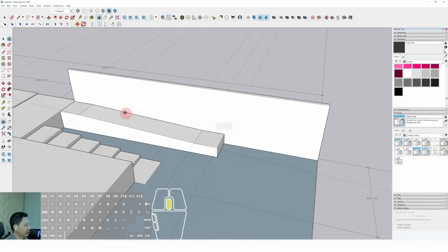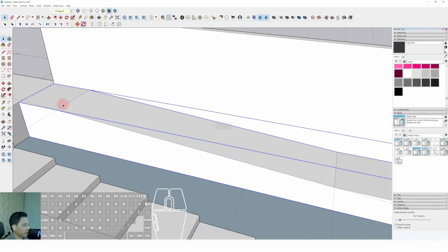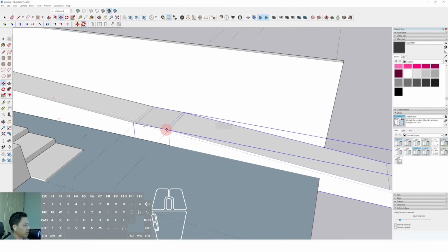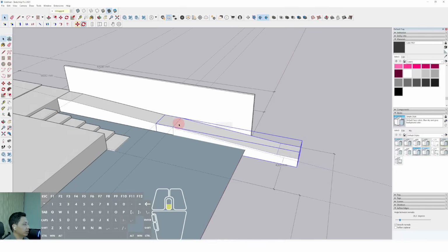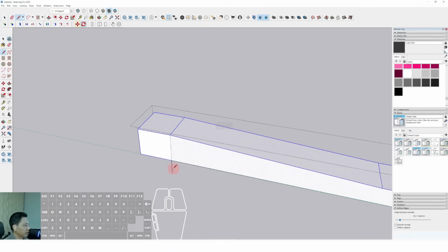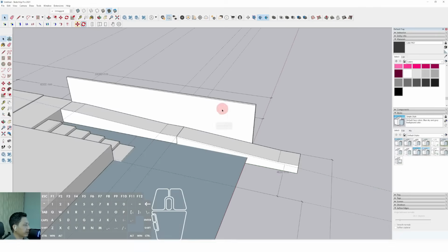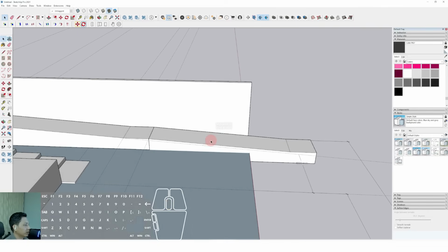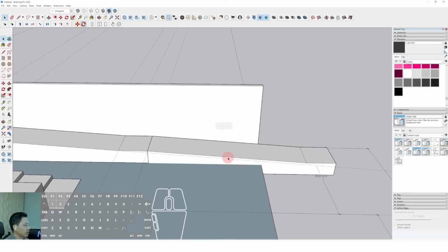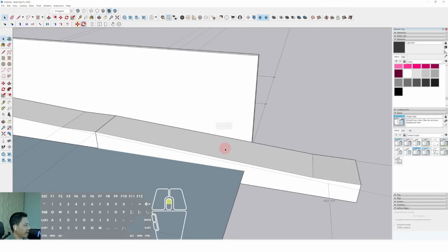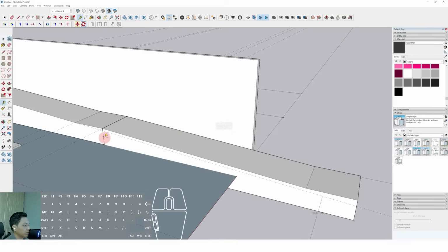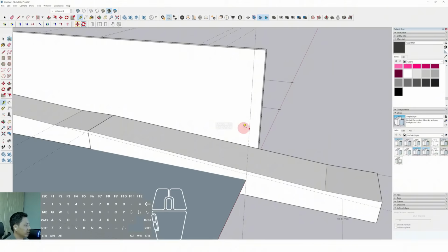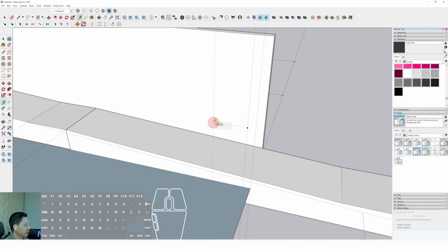And okay, then we can continue to make the another sloping. We can click this ramp and select move, tap control, and place to this position. Okay, then we can push it until the end in here, and then we can make the maneuver again in here. We can click from tape measure tool, until this position. Then we can drag 150 millimeter. Then we can click to the another side around 1.1 meter.